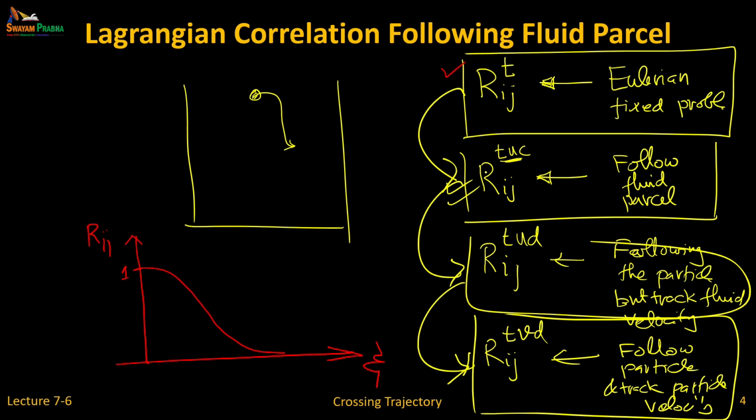For a longer time, because I am riding the eddy. When I fix the probe, the eddy may be swept out. If I have an eddy, that eddy is being swept by a larger eddy. So that fixed probe will see any eddy only for a short time because it's being swept away. Whereas when I follow, I'm riding with the eddy. Therefore, excellent, some people answered.